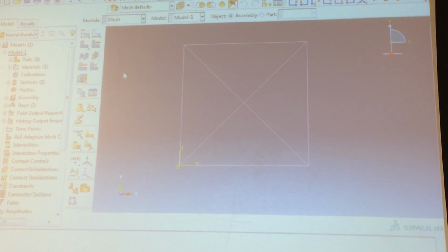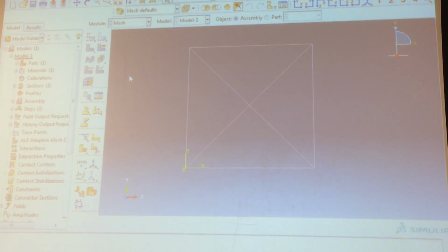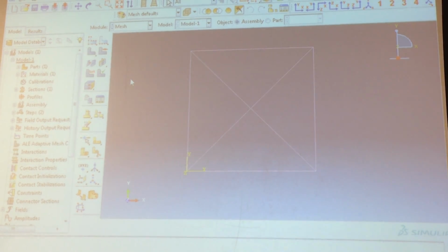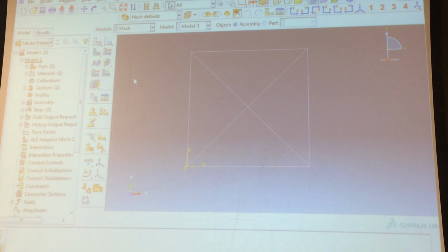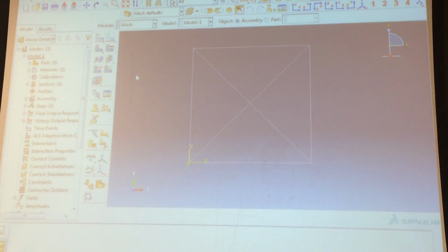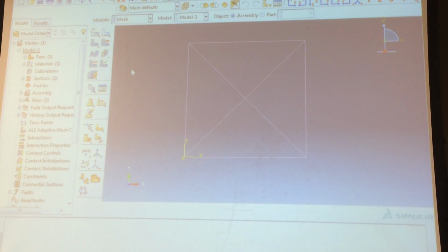Because if you break, let's say, this element into 4 parts and create an element for each part, then it would treat each part as a separate truss member, which is not what we want. So we make sure that each member gets just one element and one mesh.